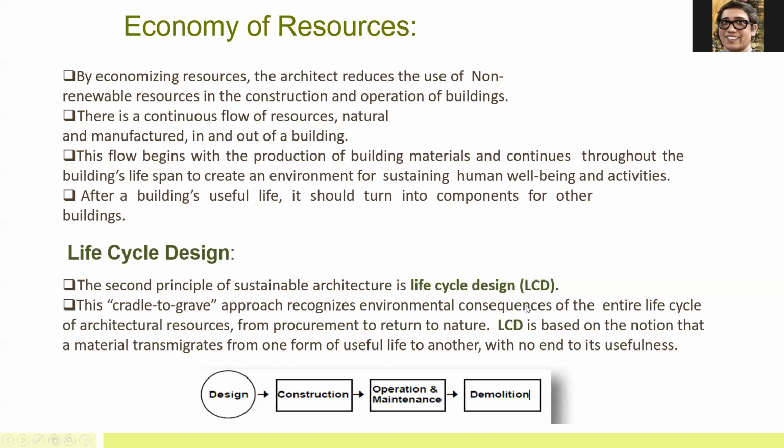So there is also a principle you call life cycle design. No? This is a cradle to grave approach that recognizes environmental consequences of the entire life cycle of architectural resources. This is from the design to the construction, operation, and then to the demolition. So that is life cycle design. If you design something and you consider that it will be demolished afterwards, and you are thinking of reusing that particular building that you are building right now, that is what you call life cycle design.